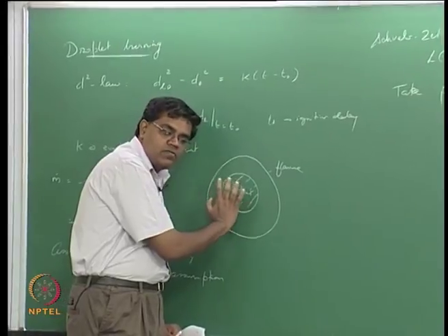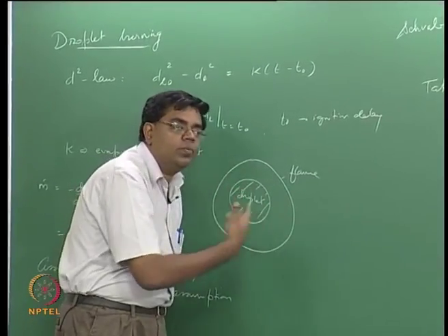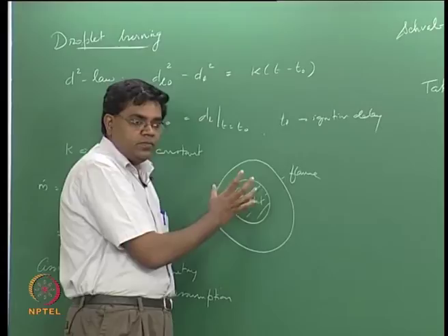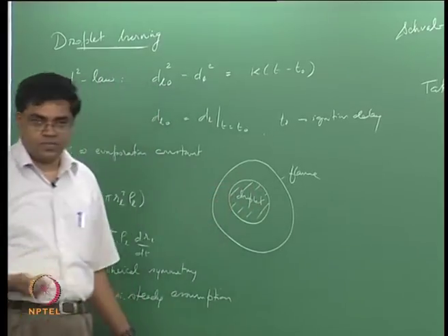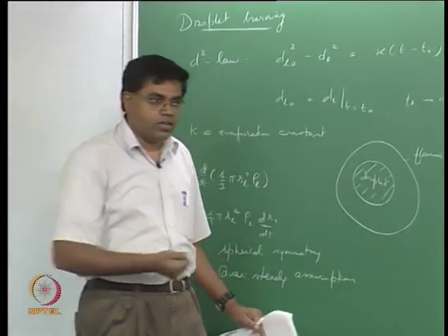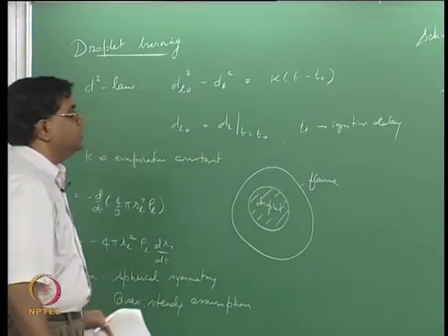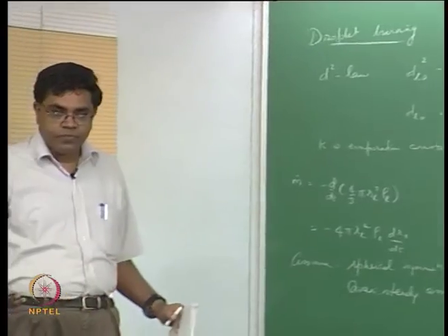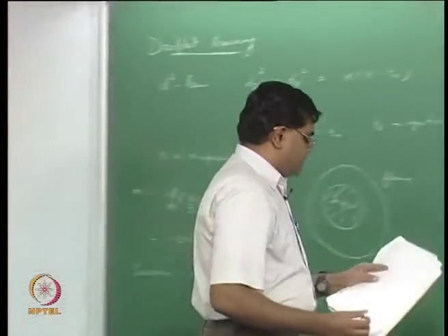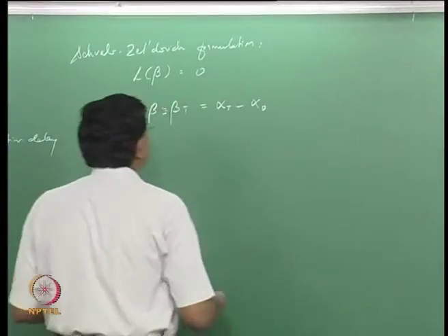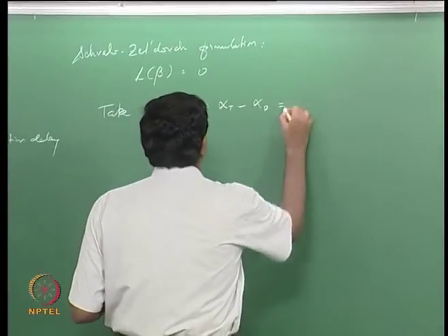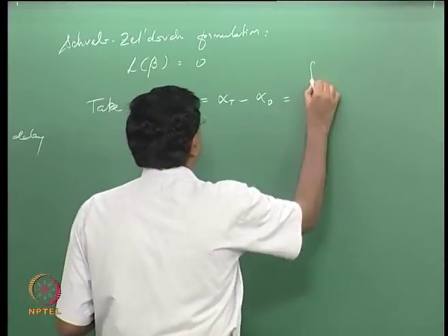If you didn't factor in the heat feedback, you would not be able to vaporize the droplet. So you need the energy balance, number one. And the oxidizing species is taken because it's purely gaseous, so I don't have any problem with it vaporizing. So alpha T minus alpha O is a good combination.